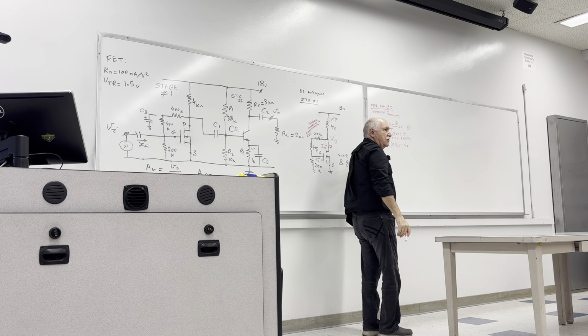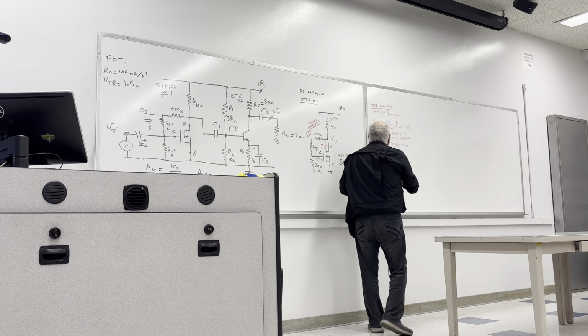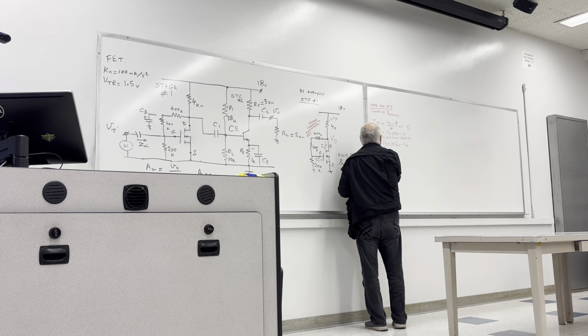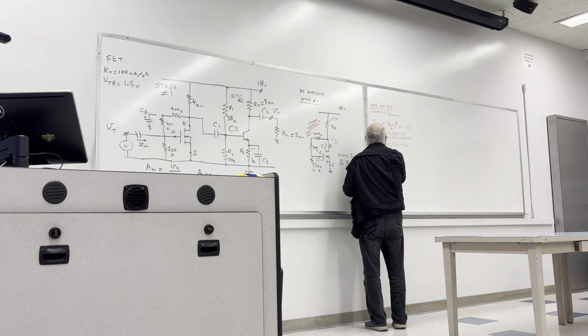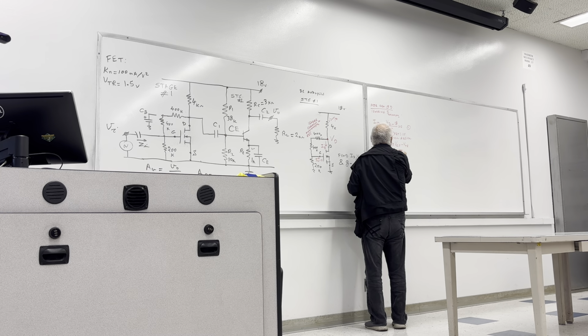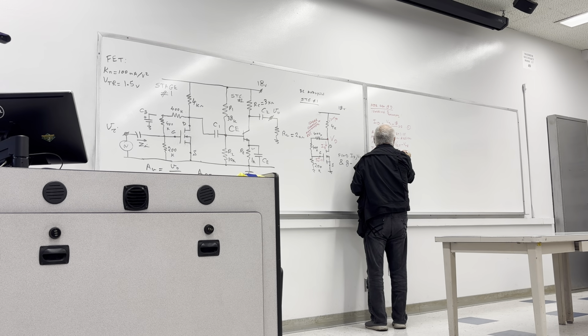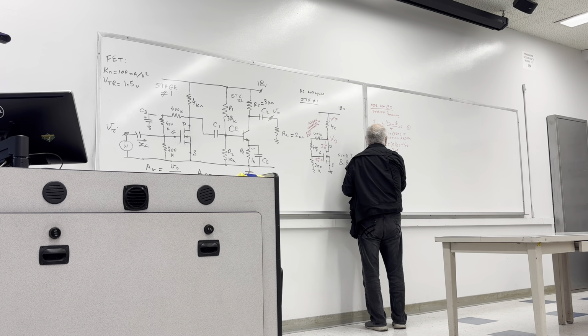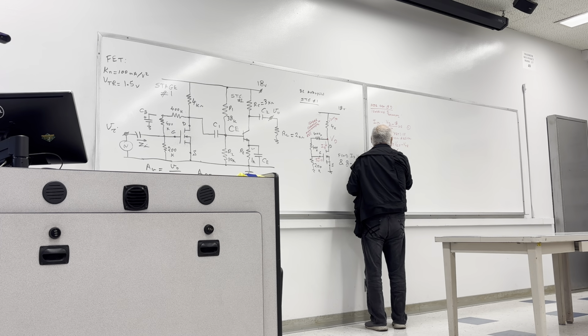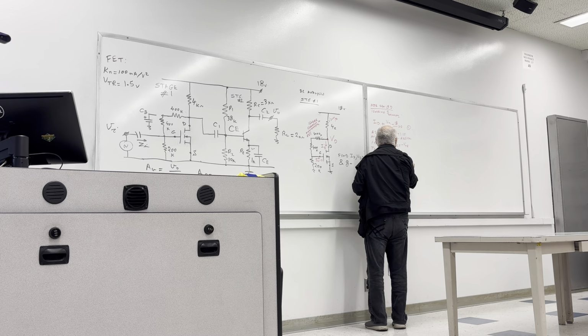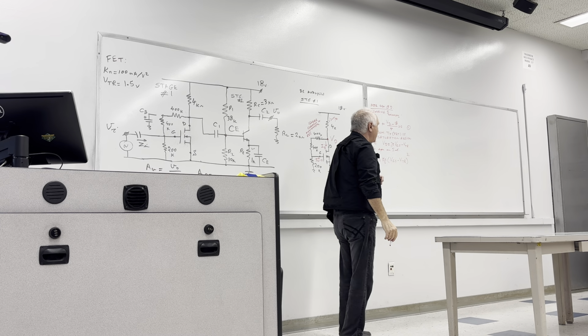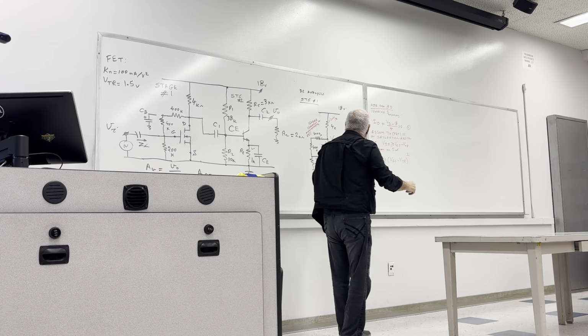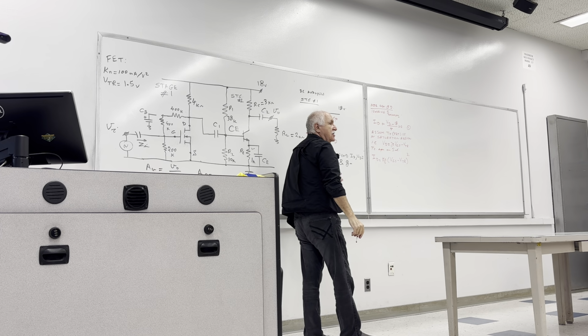That's the condition for transistor being in the saturation. Now, transistor equation. Equation in saturation. I of the D is equal to Kn over 2 VGS minus VTH squared. This will be your relationship between gate to source voltage and the drain current.